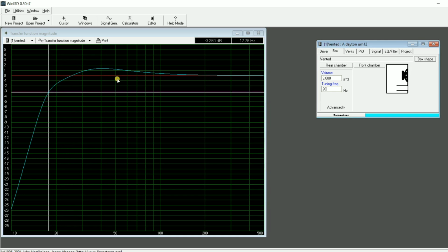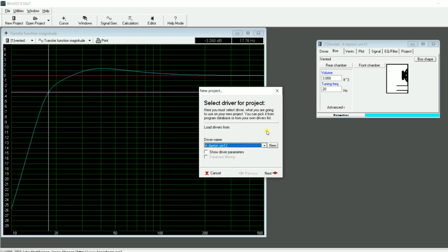So we're going to look here in a few minutes at an SVS PV13, and look at its frequency responses and see how it compares to what we're doing here. And remember, they're using EQ, or this baked in boosting, depending on what tuning you're using, to get the response, and we're not using anything right here. This is a raw response with no EQ. This is just how it looks in that enclosure we just made. All right, so we can compare one enclosure to another, let's go ahead and open another project with the same driver.